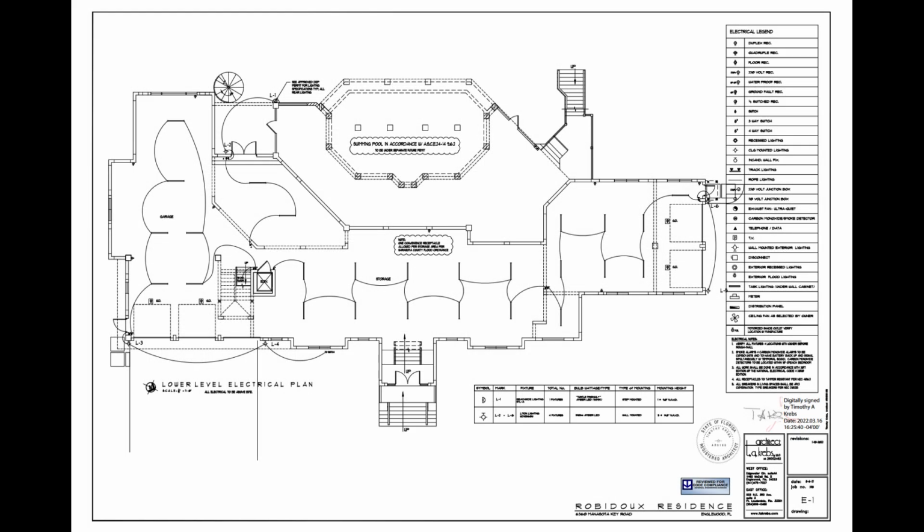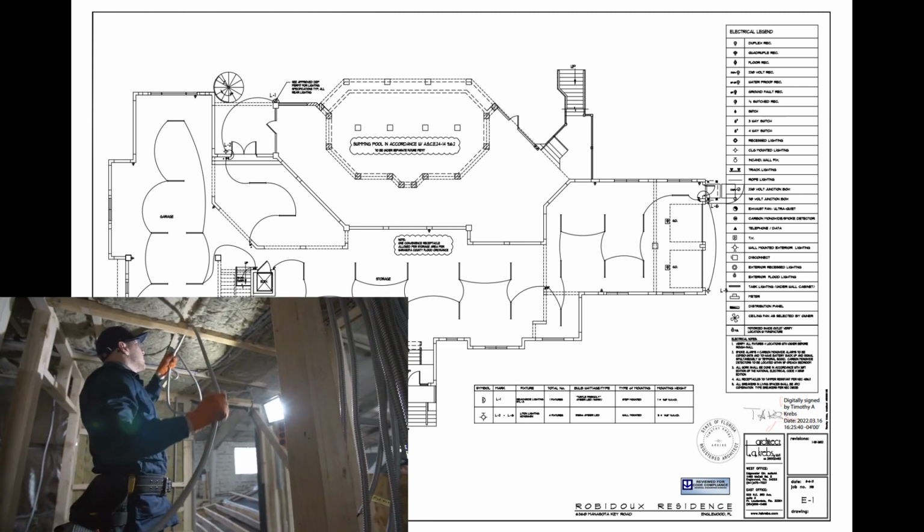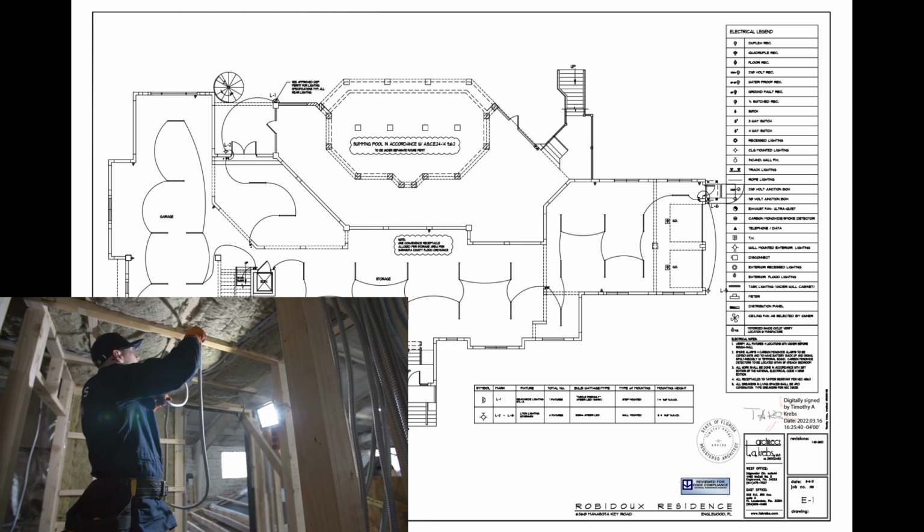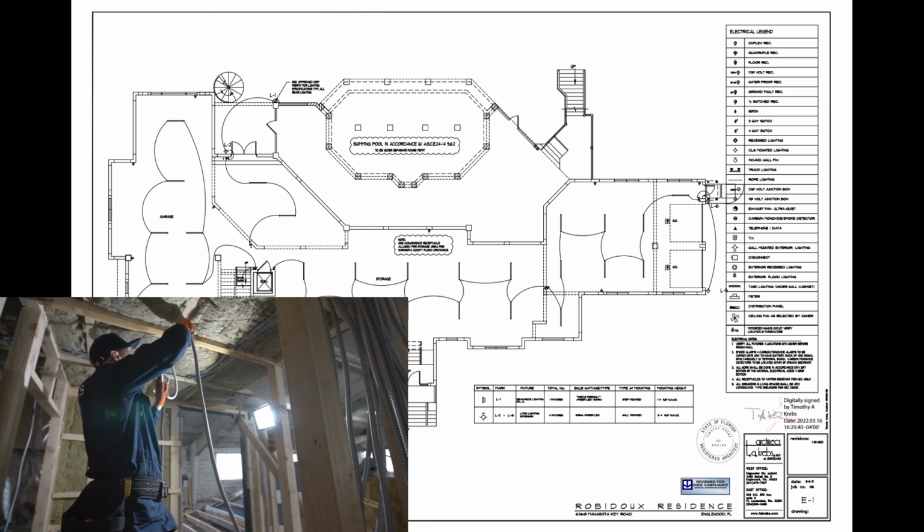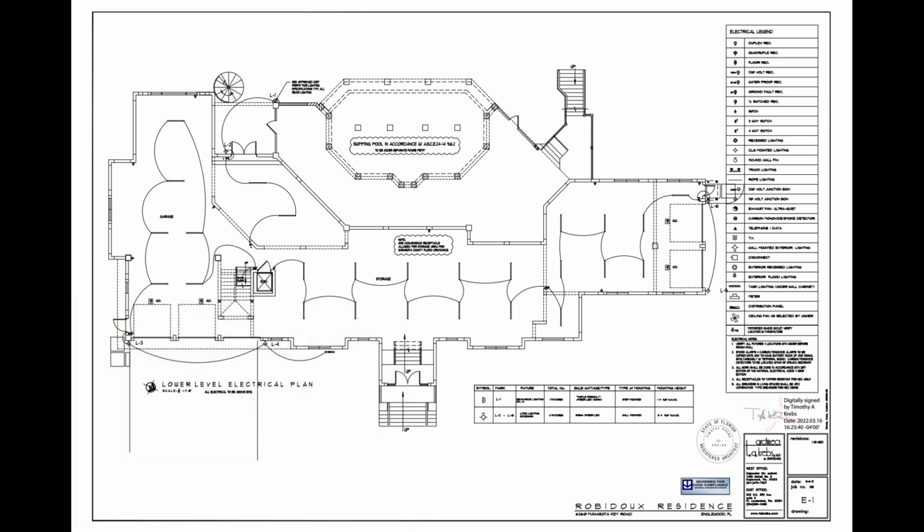Electrical plans or E sheets show electrical components and circuits within the building or structure. They usually have a legend which describes the different icons used within the electrical plan. The icons represent different electrical components or fixtures. The electrical plan is usually a simplified version of an architectural floor plan.